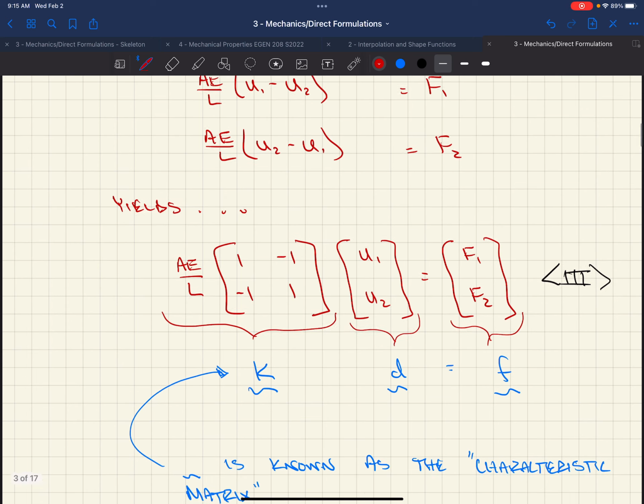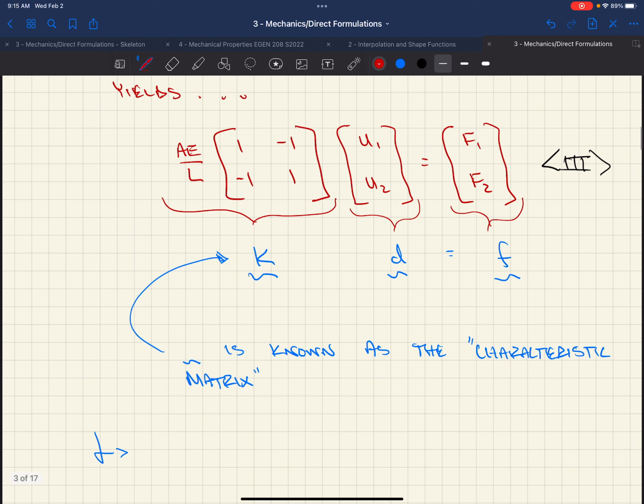So we get this nice matrix-based form of the stiffness of our element. One linear element sitting in space. Cross-sectional area of A, length L, modulus of elasticity E, and it has 2 degrees of freedom. We can just push the first node in one direction, in the axial direction of the bar, and the second node we can do the same thing.